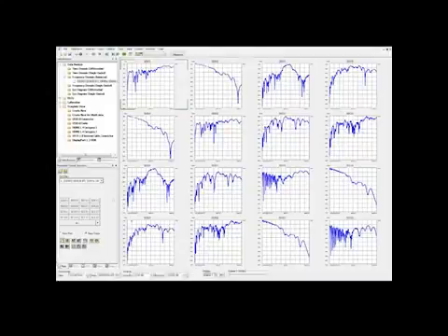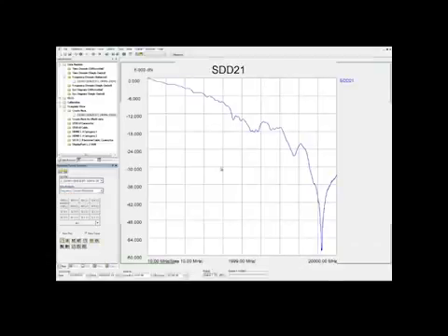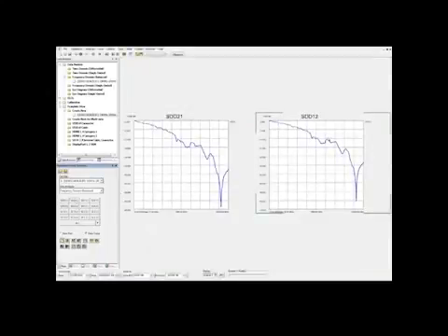Now I'm going to create a new template for this fitted insertion loss and insertion loss deviation. I'm going to do the programming, and then we're going to save the programming in the template so we can leverage that in the future. So we're going to go to frequency domain balanced, and I'm going to look at differential insertion loss, and then also the reverse insertion loss.